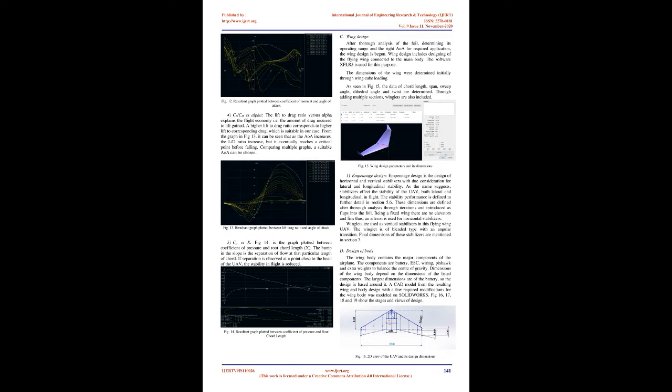The thrust-to-weight ratio varies continually during a flight. Thrust varies with throttle setting, airspeed, altitude and air temperature. Aircraft with a thrust-to-weight ratio greater than 1:1 can pitch straight up and maintain airspeed until performance decreases at higher altitude. Based on these considerations, the T-motor AT2310 2200 kV brushless DC motor is chosen in a dual setup.